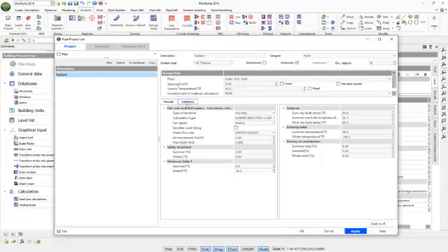For the fan coils tab, we have it broken down into several different sections. The first section being fan coils and unit heaters, calculation criteria, where the type of terminal, we have two options to choose from: 2-pipe or 4-pipe. We'll select 2. Our calculation type, we have our summer choice plus winter, or a summer selection verification. We'll leave it as a default as summer selection plus winter.